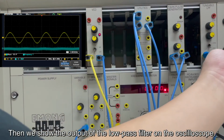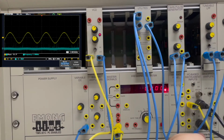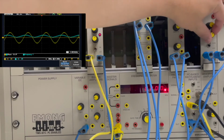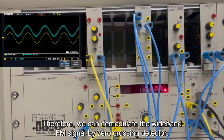Then we show the output of the low-pass filter on the oscilloscope. We reduce the cut-off frequency. Therefore, we can demodulate the wideband FM signal by zero-crossing detector.